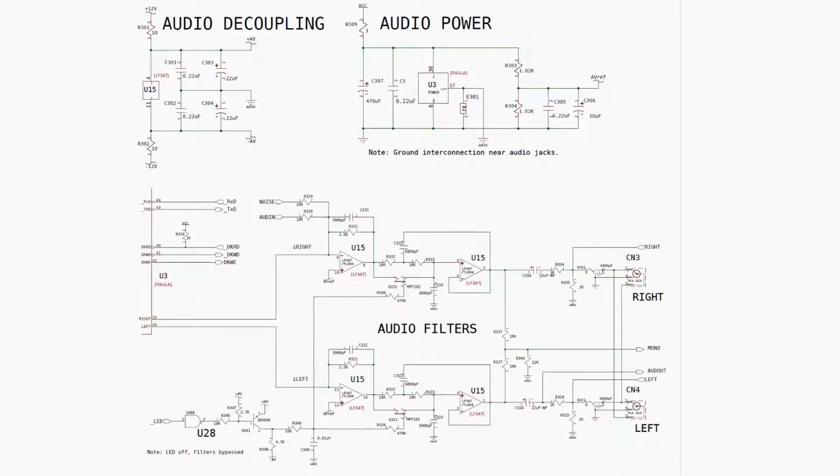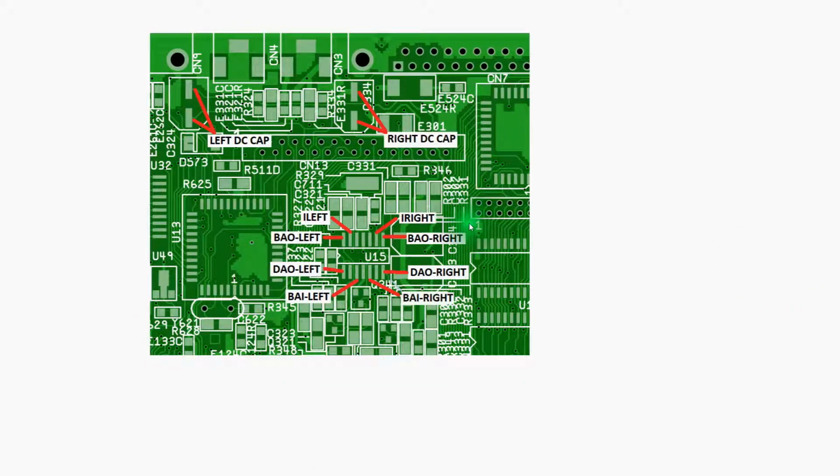So I'm going to come back around to what I just said and say it again. I do tend to spend time looking at the schematic, understanding the circuit, creating aids to help me with troubleshooting. Again, this will help me spend less time with my hand floating over the board with the oscilloscope probe or a voltmeter probe in my hand. That reduces the odds of me slipping when I'm not looking and creating a short someplace and taking a chip out.